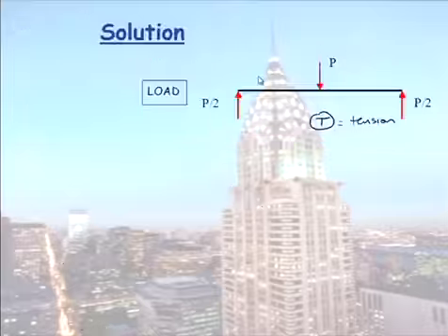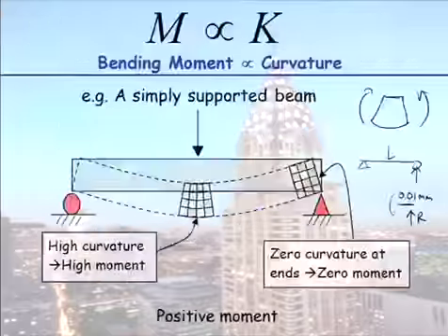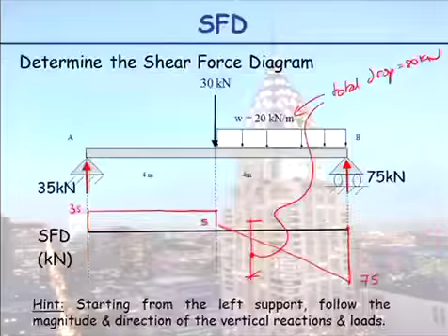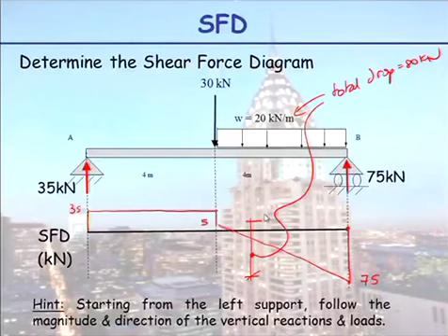If we go back to this other one back here, see my shear force diagram is sloping. What is the slope of that line there? Well, it steps down 80 kilonewtons over 4 metres. Rise on run. Yep, 20. My load here is 20.